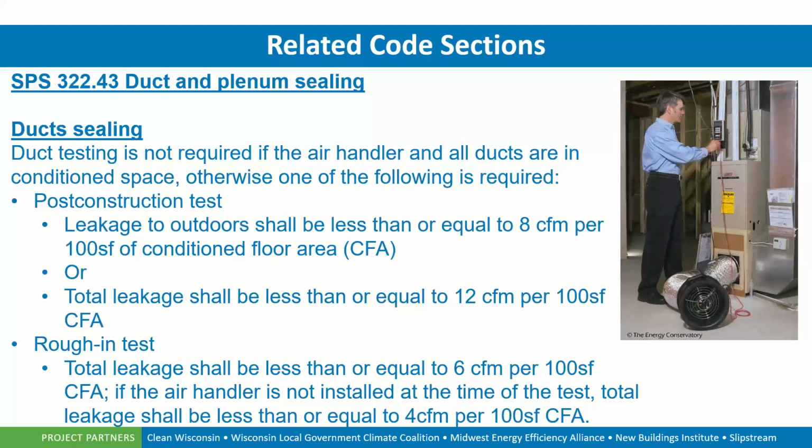Okay? Although if the ducts are extremely leaky, it may be difficult or sometimes impossible to seal those ducts by common means, whether it's tapes or mastic. So we can do a rough-in test to find out where we're leaking, get the duct sealed. You can do a post-construction test after the fact to make sure that we still achieve that leakage percentage. This is something that will be demonstrated in the future. We'll be advertising for a blower door and duct blaster demonstration a few times through June of this year. So be on the lookout for those dates if you want to come out and watch how Robbie sets up the blower door and duct blaster and runs a test on the HVAC system in the home.